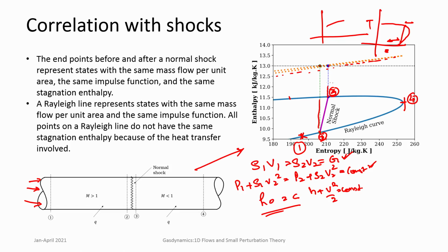That undergoes no change, because a shock does not affect the enthalpy. Enthalpy is constant across a shock. At any location, it just changes the flow from supersonic condition to subsonic. So, it moves like this, goes up and goes over like that, but it does not change the total heat that is getting added.